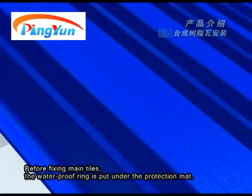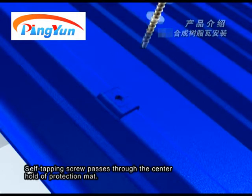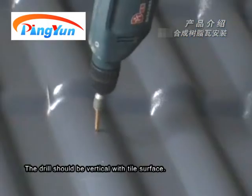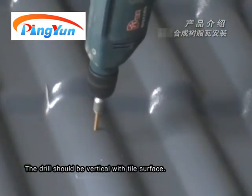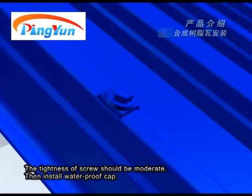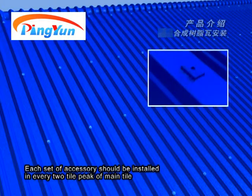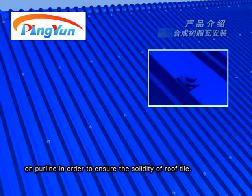Before fixing main tiles, the waterproof ring is put under the protection mat. The arc side of the protection mat should be on the bottom side. The self-tapping screw passes through the center hole of the protection mat. The drill should be vertical with the tile surface. The tightness of the screw should be moderate. Then install the waterproof cap. Each set of accessories should be installed in every two tile peaks of the main tile on the purlin in order to ensure the solidity of the roof tile.